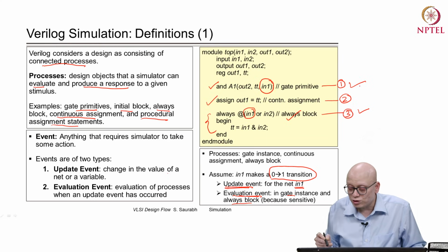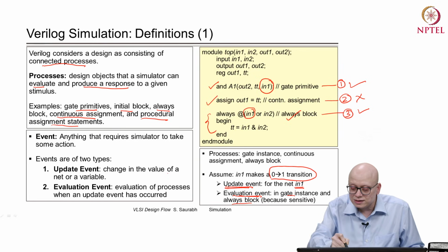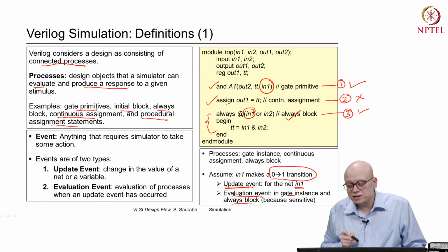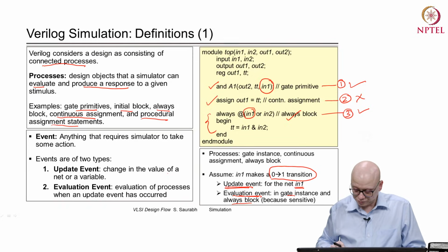In these two processes, there will be an evaluation event, but there will not be an evaluation event in this continuous assignment statement, because it is not sensitive to in1.